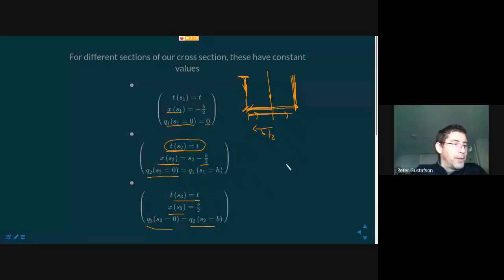All right, so Jeremy asks a question. Ideally, shear loads are placed at the shear center. Bending loads are placed at the centroid. Well, not exactly, Jeremy. That's a good question. One thing you have to keep in mind is that shear loads are the resultant shears on the cross section. So they contribute to bending.